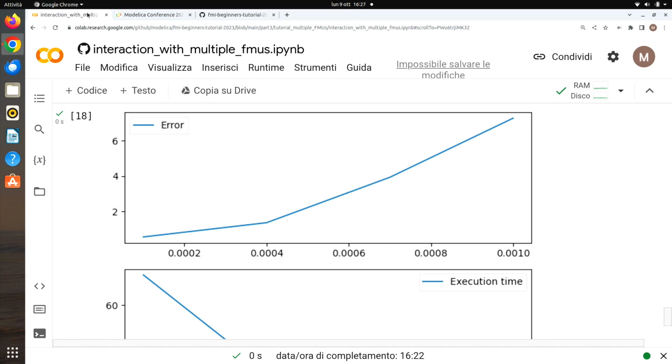And the FMI standard, can it also give some error? So it cannot give back some error of the individual... No, that you have to do outside. There is the return early function, where an FMU can return earlier to say the error is too large, or in case of events, for example, but it's more about the master, the co-simulation algorithm around it. Yes.